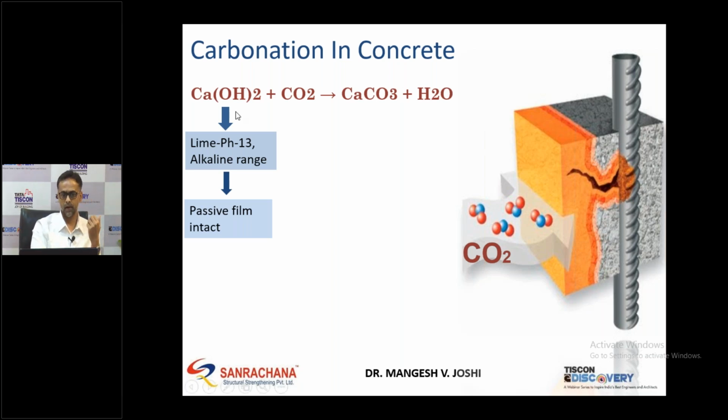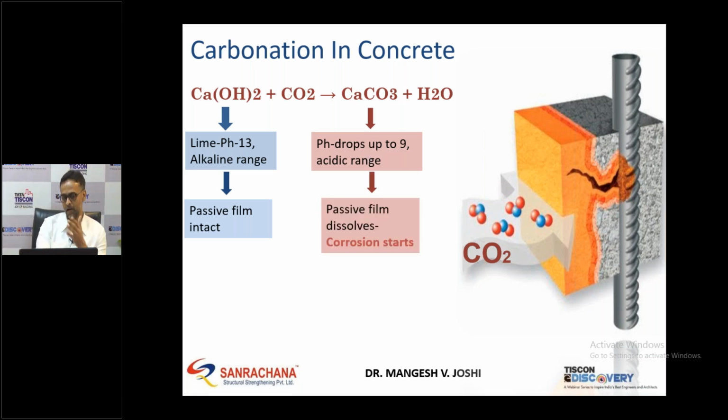The moment it reacts with carbon dioxide, it forms calcium carbonate, and your pH drops to 9, gradually and slowly, and it tries to go into the acidic zone. And the moment the pH starts reducing, your passivation film gets dissolved and corrosion starts. So this is a preliminary reason for corrosion in RCC.